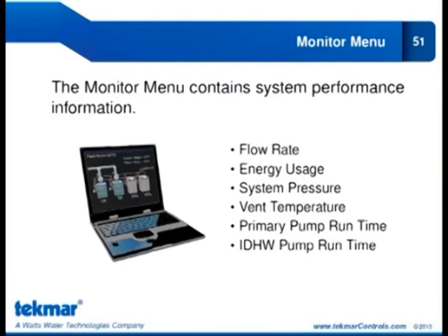Yeah, that plastic one I don't think is rated over 120 degrees F, so you might be careful applying that in a heating system. Yeah. So definitely the stainless steel ones, a little bit more money, right? And actually quite a bit more on the larger sizes, but we'll probably look at getting those ones. The problem is just availability, because you can only source them from Denmark. But again, we want to at least carry a couple models here.